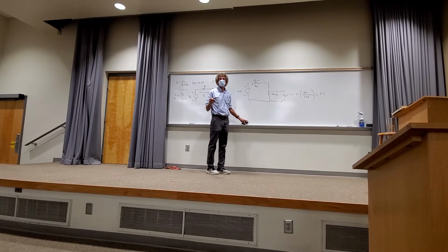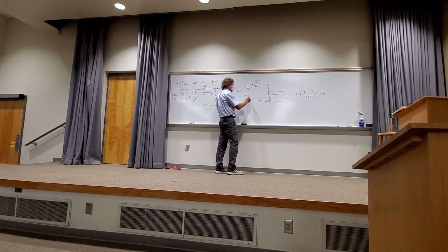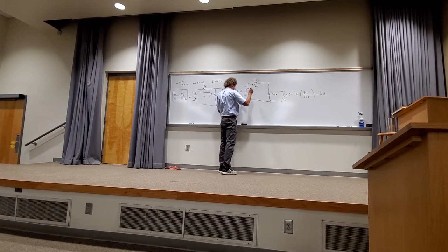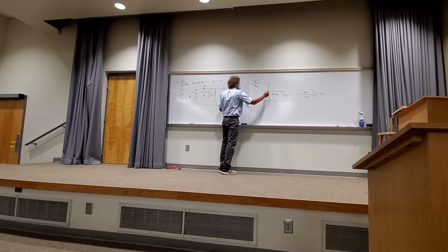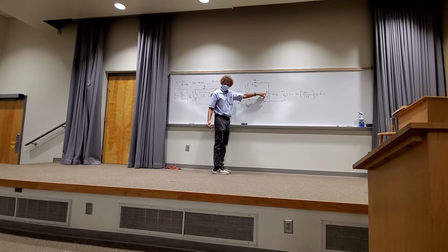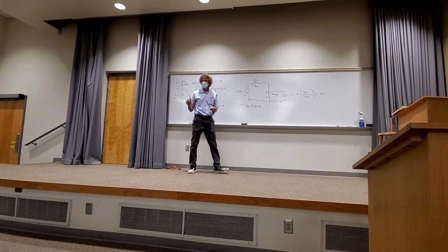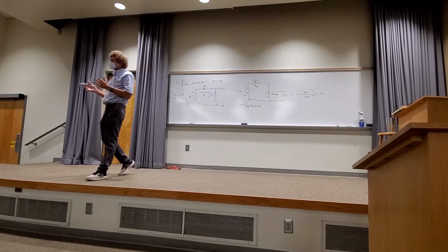what we know about Kirchhoff's voltage law, as it's called. The sum of the voltages around any closed loop is 0. If I start here, I would get an increase of 10, right? If I start here, it's an increase. Do you all agree? I went from a negative to a positive. Here, it's a decrease, minus V40. And here, it's going to be a decrease also, because the polarity, the way the current enters, would be this way. That's where the positive polarity is, right? And we know that that voltage is 6, right? Correct? That would be using Kirchhoff's voltage law to get that voltage.